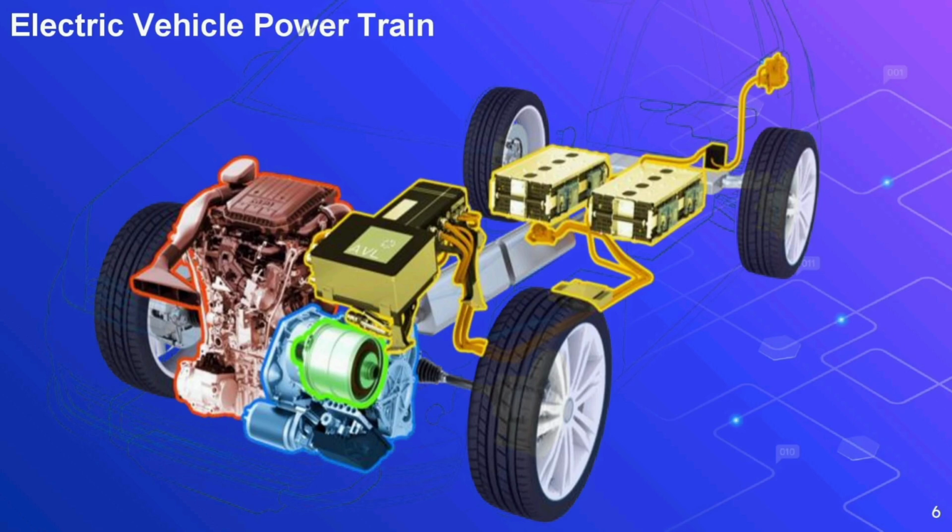A conventional engine-driven vehicle uses its engine to translate the fuel energy into shaft power, directing most of this power through the drivetrain to turn the wheels. Much of the heat generated by the combustion cannot be used for work and is wasted, both because heat engines have a theoretical efficiency limit. Moreover, it is impossible to reach the theoretical efficiency limit because some heat is lost through cylinder walls before it can do work.